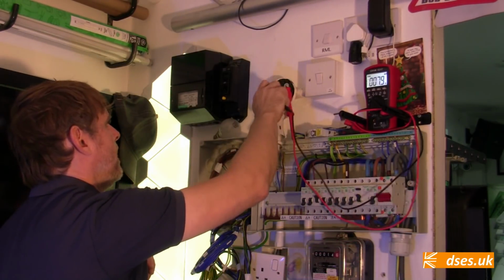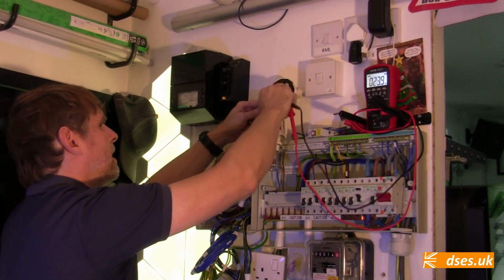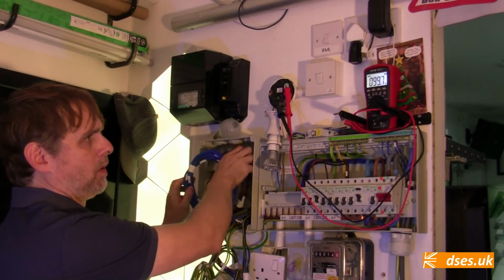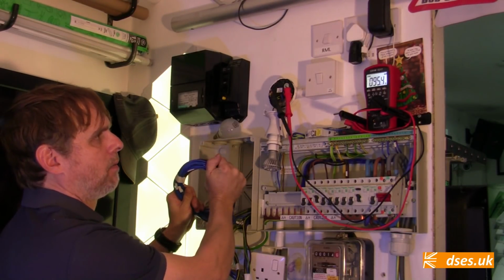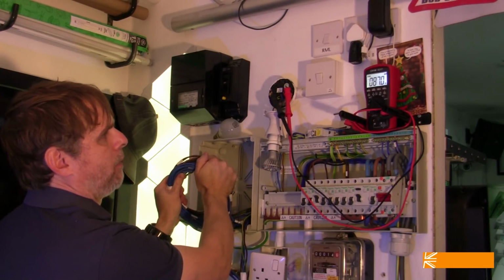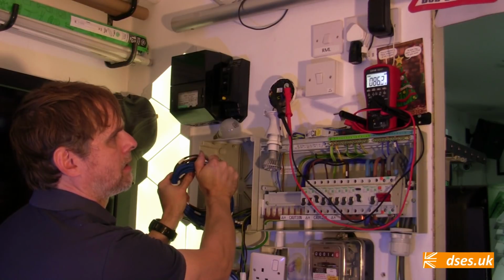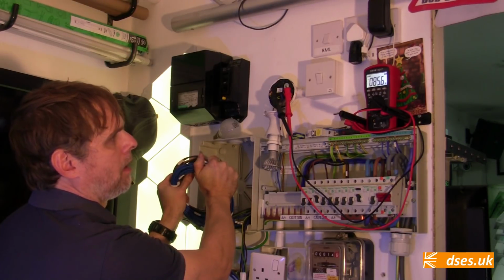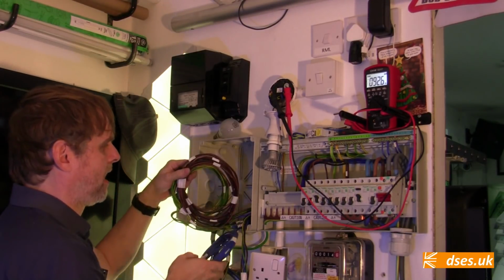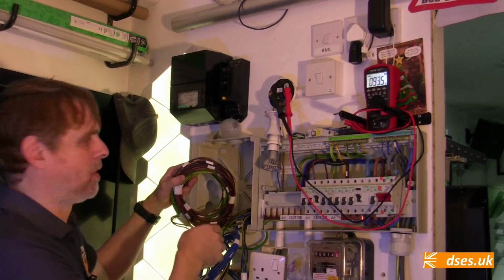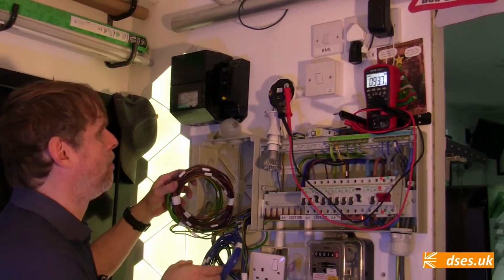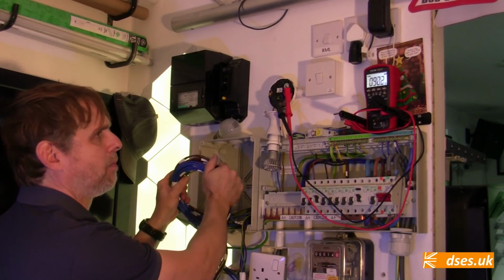So we'll stick the voltmeter on here, and we're reading nearly 100 volts. If I introduce the neutral to the line wiring, we can see it drops down. We're down to 95. If I bring the CPC in as well, then we're already down to 86, 85. I'm never going to get it down to 0 because we still have this capacitive effect going on. Only by running these cables so that the two circuits are separated out from each other will I get it down to a 0 level and completely eliminate the problem.